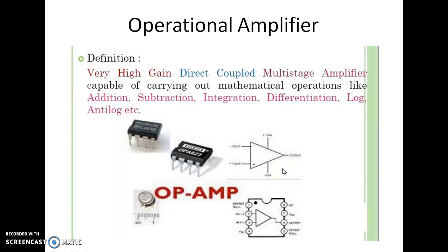A careful look at the circuit symbol of the Opamp reveals different things. An Opamp has two input terminals, one output terminal and two supply voltage terminals. We can apply the input voltage which is to be amplified to any one of the two input pins connecting the other pin to ground, or the input signal can be connected between the two input pins differentially.